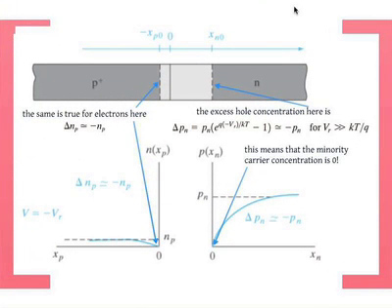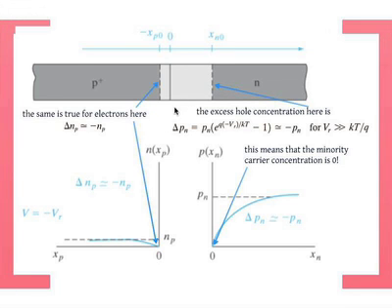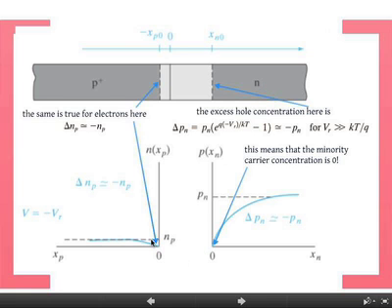Okay, the picture, if you look again from the picture that we had before, is the opposite of carrier injection. Okay? It is carrier extraction. You pull the carriers out to the other side. And let's see what that means. So you have a P plus N junction here. Okay? If you look, when you apply reverse bias, of course the depletion region gets bigger and you increase the field. Okay? When you increase the field, what happens is that any carriers that accidentally get here, they get swept across. Right? You increase that drift field, the built-in field, essentially. Okay? And you essentially lose carriers from one side.